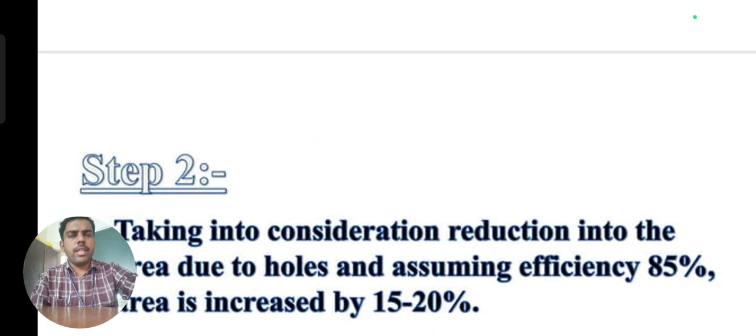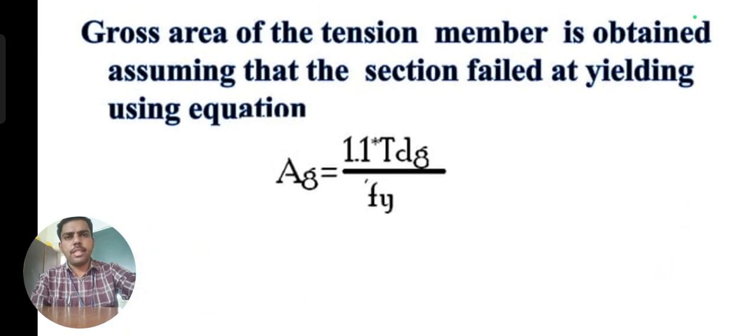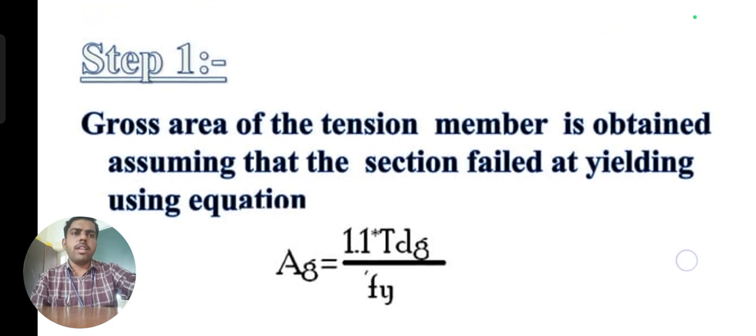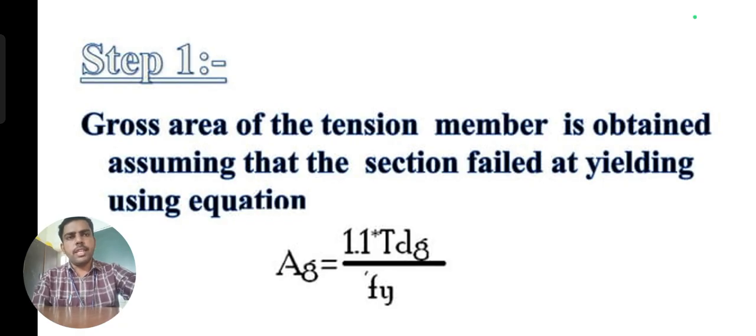With this type of tension members, there are leg angles and splice, which is one of the extra plates I have to provide in that particular scenario. This plate improves the strength of that member, and next, coming to splice and leg angles. Leg angle reduces the length of the member for saving material. All these design procedures you have to keep in mind, and just follow these few simple steps, and you can find the design of the tension member.